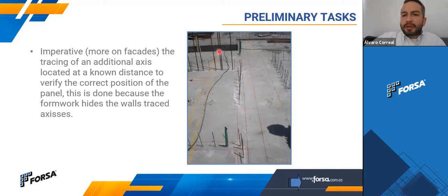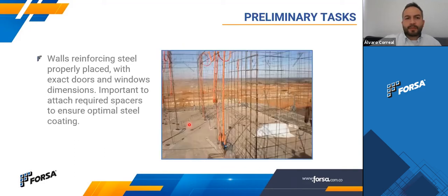There is something very nice also in this picture, and it is these yellow lines. I hope you can see them. These yellow lines are basically showing us the tracing of the hydraulic piping. This is to not damage them when you have to drill for these studs, or if you have to drill to install braces to give the verticality for the walls. So this is a very important one to do.